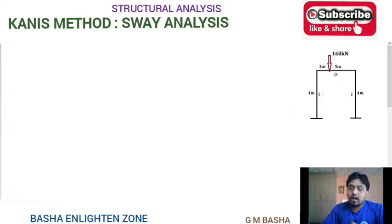In this lecture, I would like to explain another example based on the Kani's method. See here, this is a portal frame, both ends fixed, and there will be an unsymmetrical loading, equal moment of inertia and equal heights of the column. This problem comes under the sway analysis. What are the conditions here for this problem to be a sway analysis? Unsymmetrical loading.